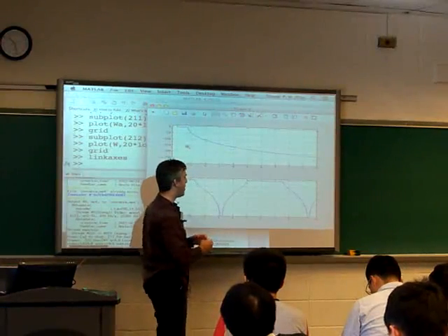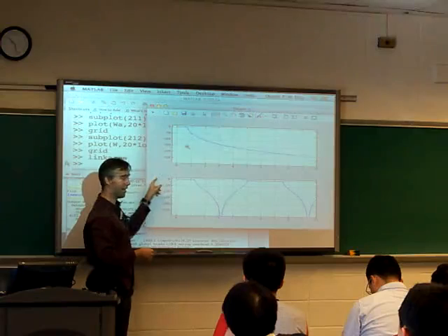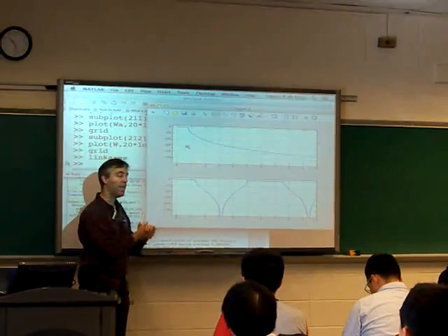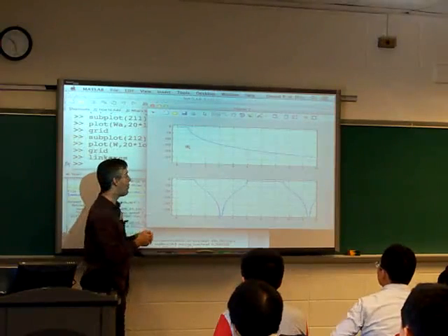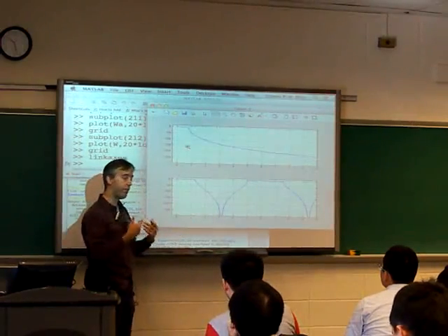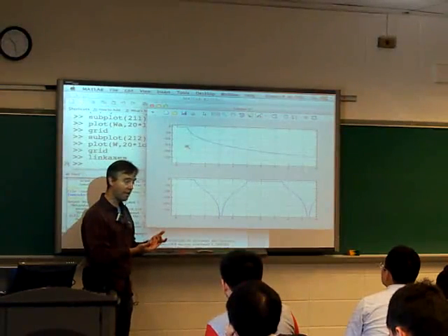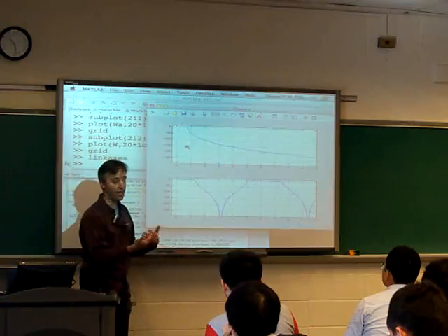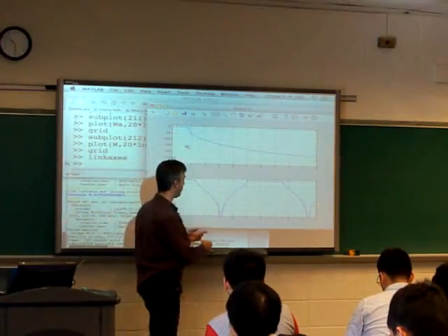Okay, you know, I could have plotted over here, and I've got this symmetric passband for negative frequencies. And so let's not forget what negative frequencies mean. The reason we plot only between 0 and pi normally is because for a real-valued system, the Fourier transform is going to be conjugate symmetric. And so the negative frequencies are going to have the same magnitude, and the negative of the phase.